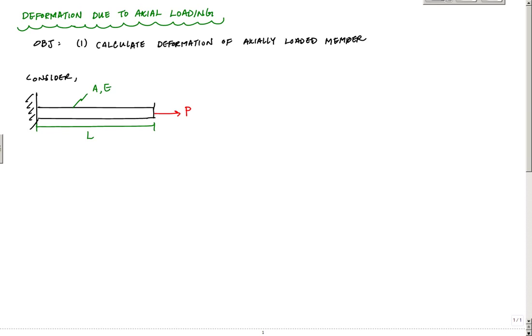And I know that when I want to examine this on the inside, I'm going to end up drawing a free body diagram. If I make a cut at that blue line and I look at the right side of that cut, I would see that I have this external force P, and all the way across, anywhere, I have this internal normal force, which is equal to P. And you would tell me that the stress on this cut, at this face, is equal to N divided by A, which in this case for just a single axial load is P over A.